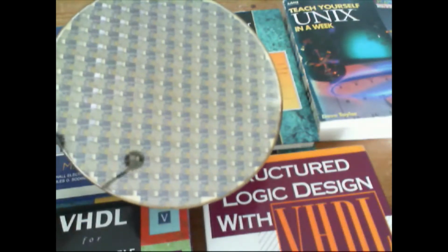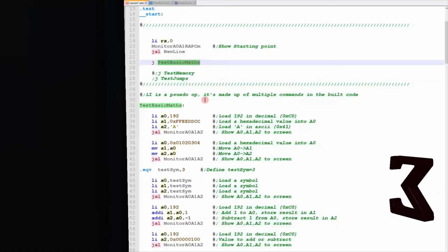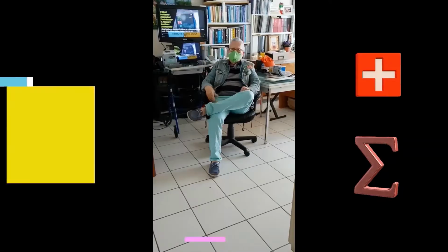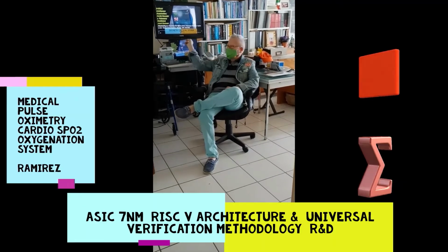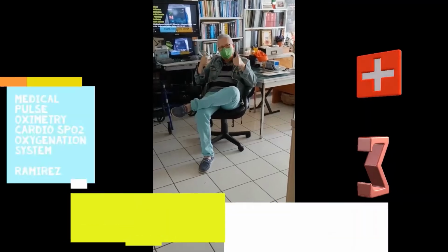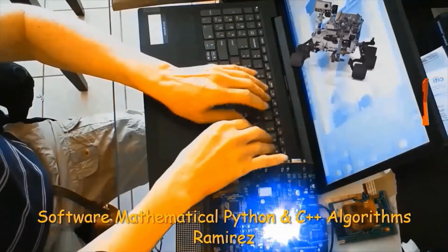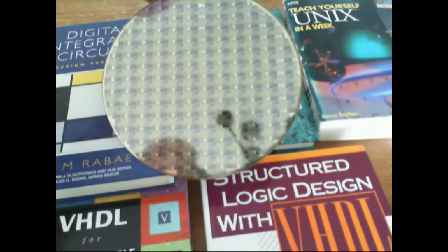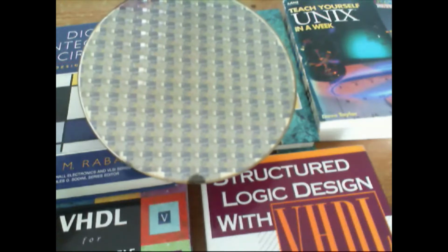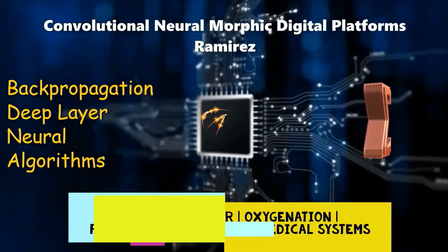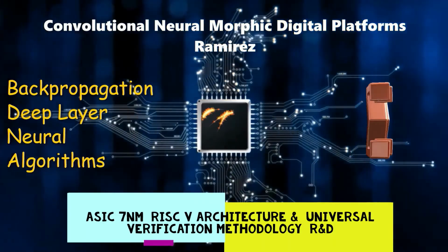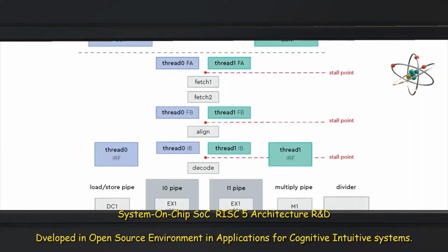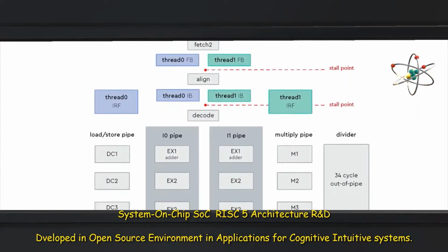In parallel, I completed and generated synthesis scripts, synthesized with reference to the library, provided scan insertion and ATPG fault simulation, and also performed the final timing and power analysis. Also in parallel, I provided functional verification with a reference simulator, developed and ran multiple test configurations, and measured test coverage.